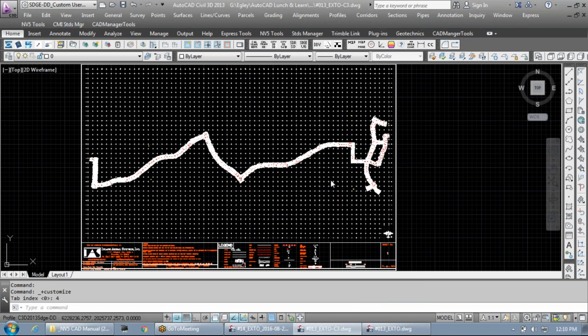Talked a little bit about dimensions. There really shouldn't be a need to override your dimension. So don't get in the practice of overriding the actual dimension. Everything that we draw here should be in a real-world coordinate system and real-world dimensions and lengths. So if you're finding yourself overriding dimensions, check your drawing first. Make sure you're drawing it accurately.